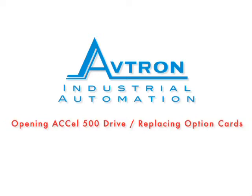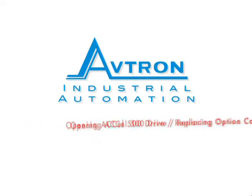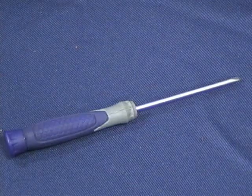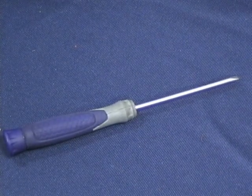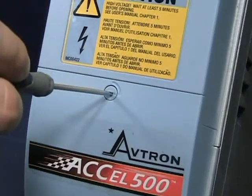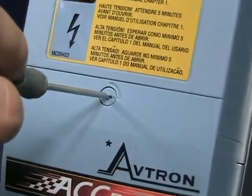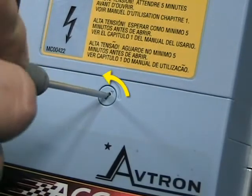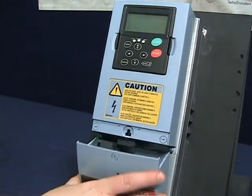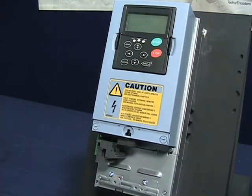Opening the ACCel500 drive and removing or replacing the option cards. To open the front of the ACCel500, you need a small slotted or flathead screwdriver. Insert the head of the screwdriver into the slot located on the bottom cover, and turn counterclockwise to unlock it. Now you can remove the bottom cover by hand.